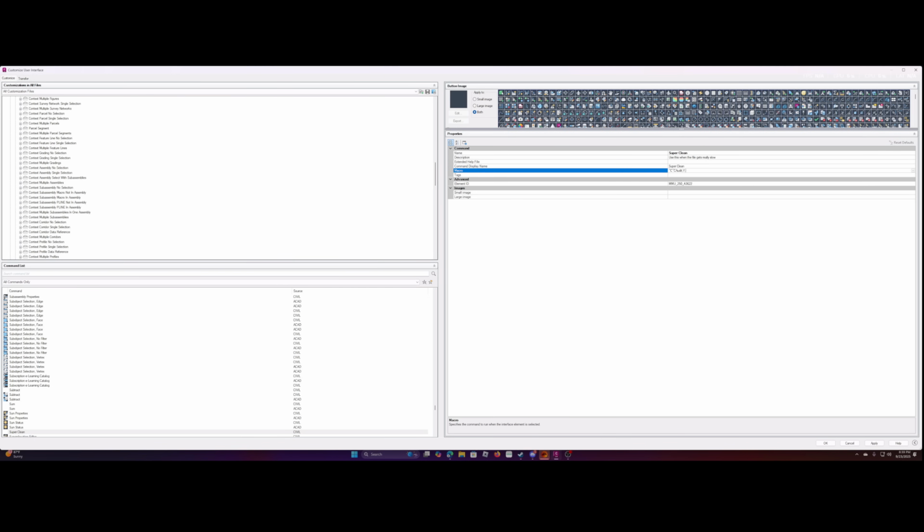So if I was to leave this just like this and run this command, all it would do is complete the audit, it would never even prompt us to say yes or no, right? It would just run through, okay? So now that I have hit enter and it's probably going to run this command, I don't have to stop there. I can add another command to it, so I can string commands together. So here I could add dash purge, because typically that's what I would run next, right? I would run dash purge.